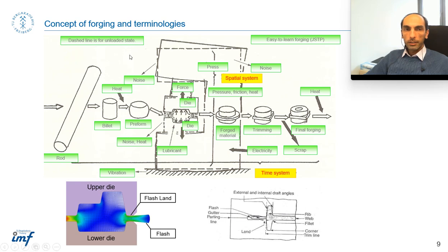and after applying, you can see it even shows some deformation in the structure of the press. It's interesting. Maybe you couldn't imagine that when you're forging a material, even the machine has some deformation. Of course, this is exaggerated to see, but it exists. So the structure of the press is important, and the stiffness is important.